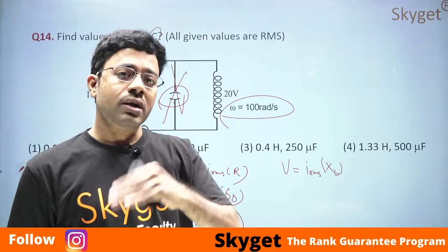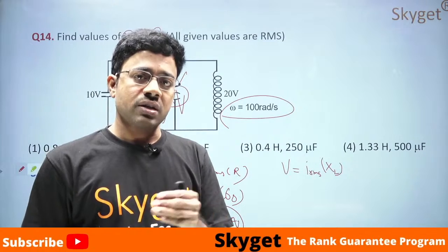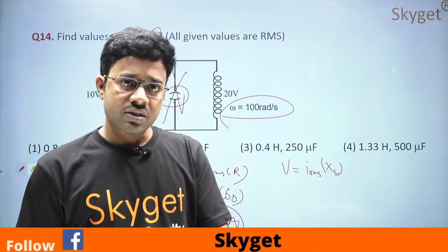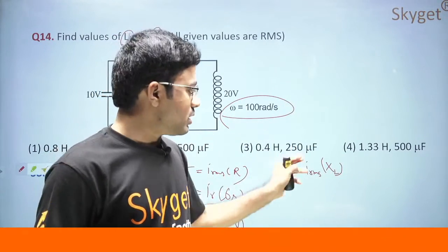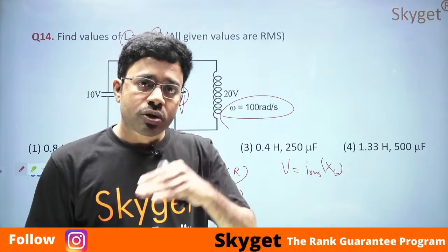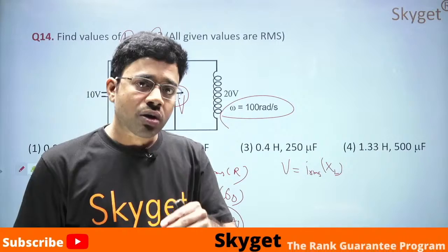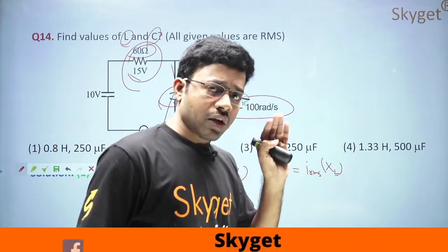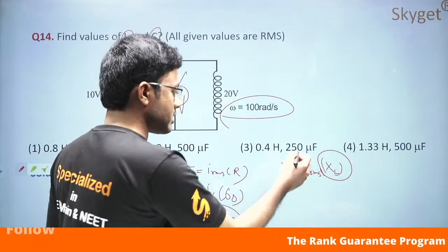It is not like the general resistance offered by a resistor, where because of its resistance the current gets converted into heat energy. But in case of the inductance, it will produce back EMF. Because of that back EMF, it is offering the resistance to the given supply or the given value of current. So that is called the reactance of the inductor, that is XL.